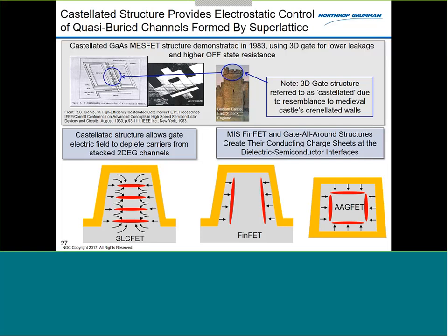So I need to put an insulator around all of this. So I'm using an insulating gate, which makes this almost like a MISFET, but it also gives me the opportunity to potentially exploit creating an inversion layer when I go to forward bias.